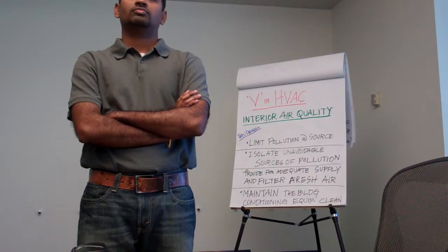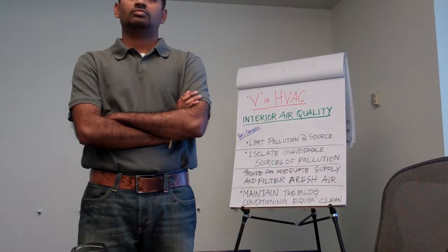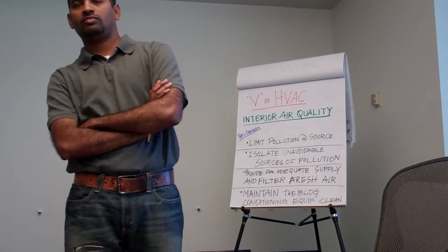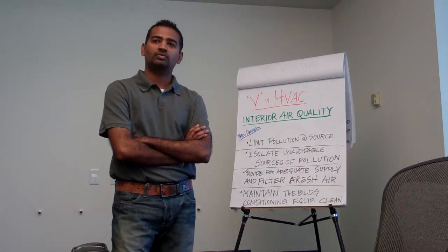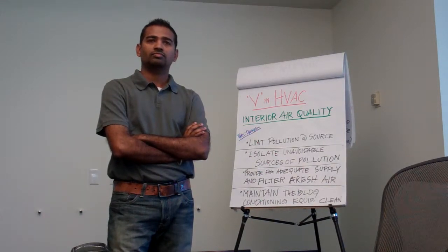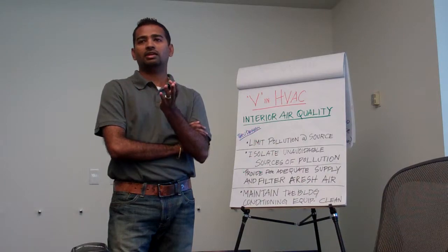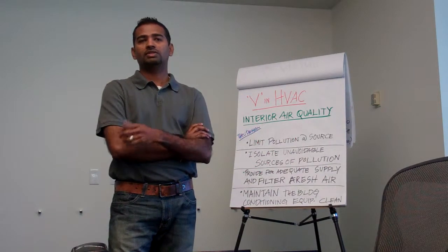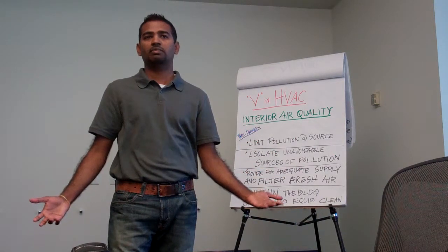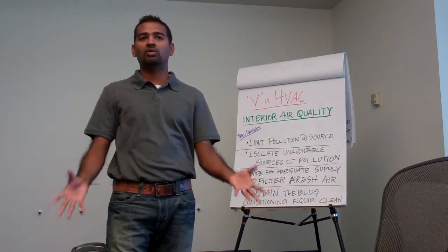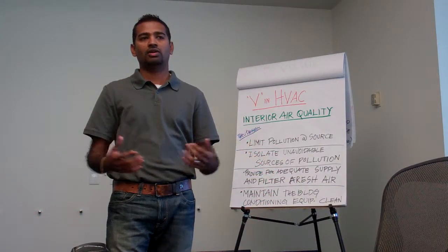So the current ventilation codes are, part of it is by area, part of it is by occupants. Right. So you can reduce your CO2 ventilation for the occupants down to the minimum of the area, which is like 0.06 CFM a square foot or something. Very minimal. That area CFM per square foot is based on the assumption that we will have some carpet, materials, paints that will be expelling VOCs automatically, always releasing volatile organic compounds.